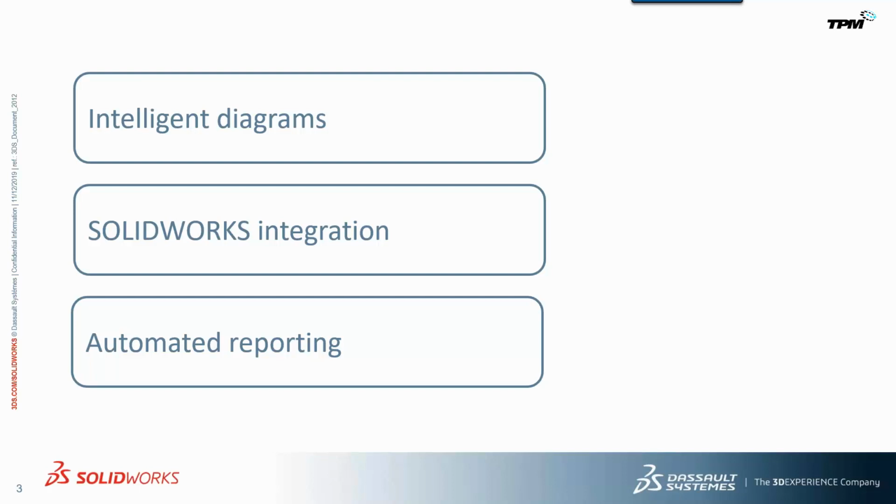The last step that we want to talk about is usually where the rubber meets the road. It's reporting and documentation. Electrical and P&ID in particular have much more regimented, strict requirements on what that report looks like from a bill of material standpoint, calling out lengths of wire, calling out lengths of pipe, and then the components within the system. So our reporting tool really is what wraps this all together.